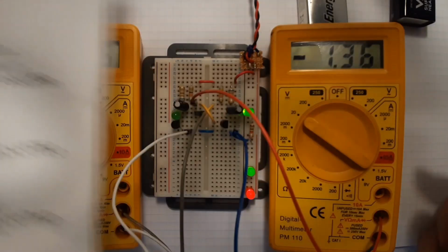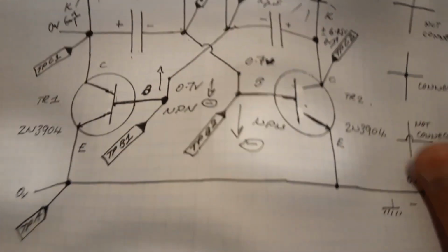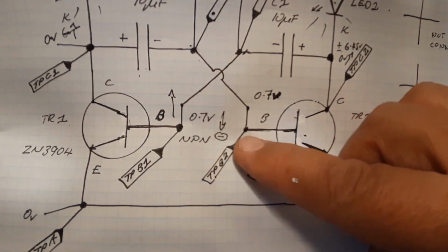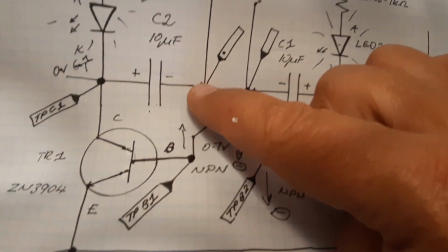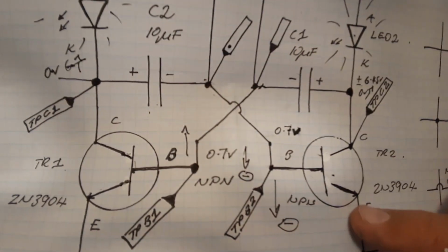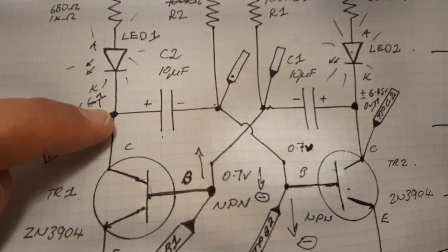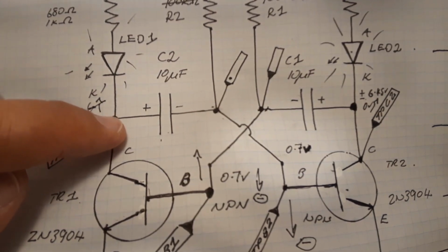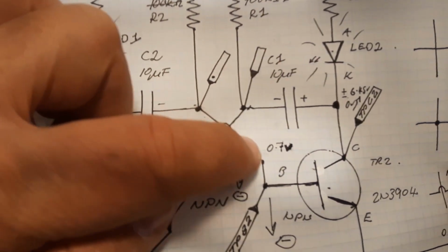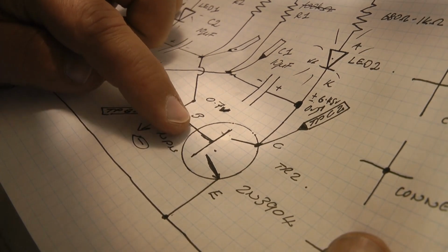And we've connected the meter on this side to the test point of base 2, probably more like there. And so now we can see how when this transistor comes on, it pushes this voltage down to 0 volts, and at the same time, on the other side of the capacitor, we've got this deeply negative result which switches that transistor off.